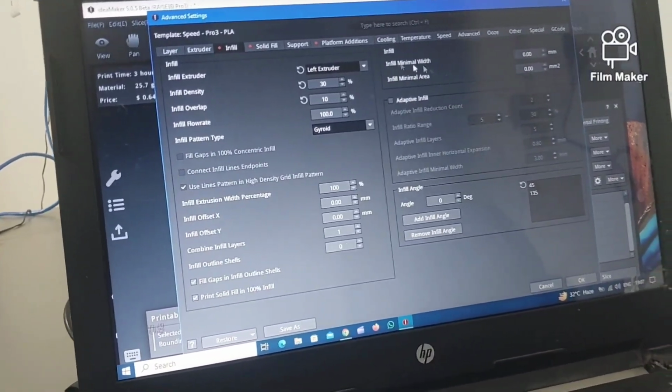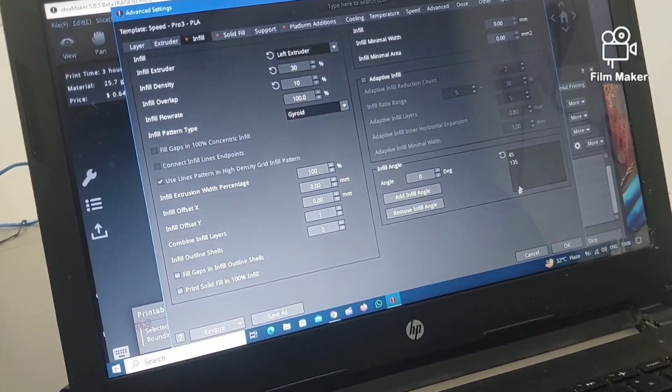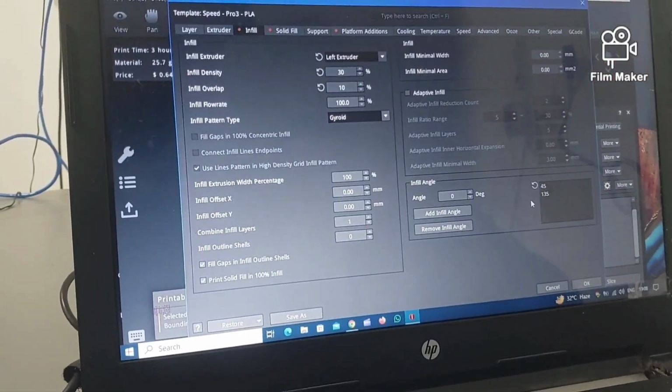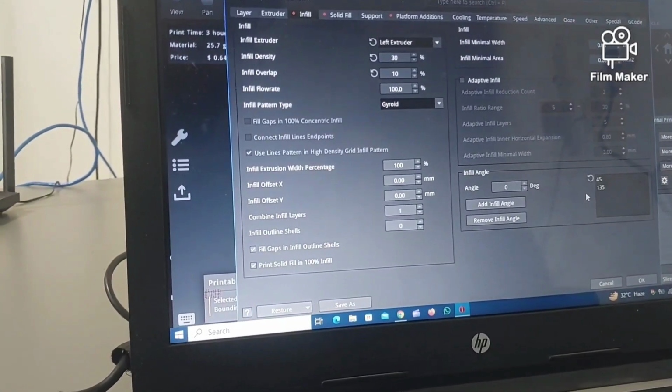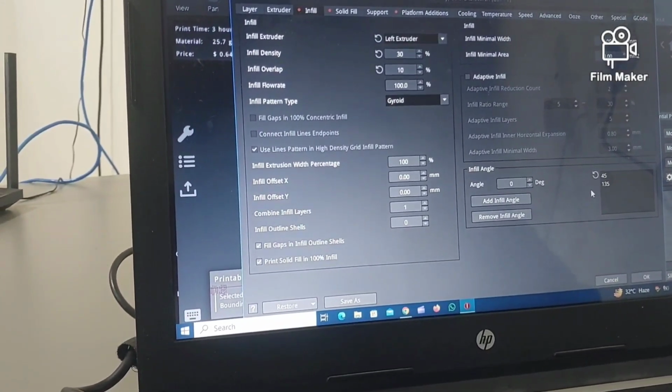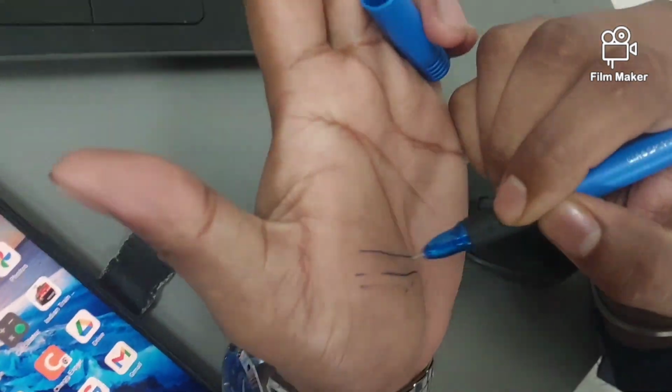And so after that, the infill angle, when the printing extruder will move, filling or overlapping through the angle of 45 degrees and 135 degrees, I am using. We can change to 0 degree, 90 degree. So after that, here I will show the strip, at first strip,